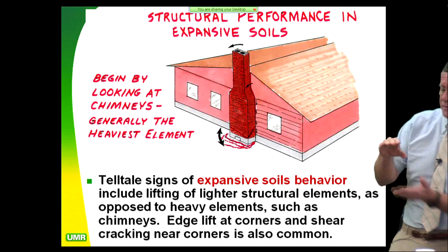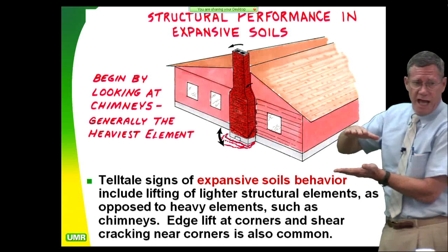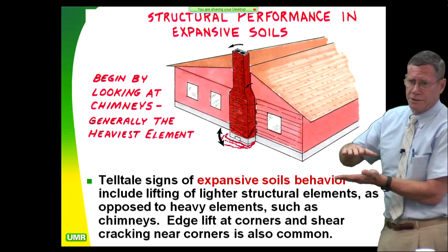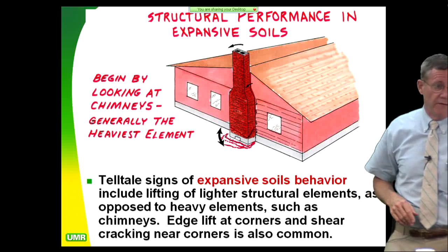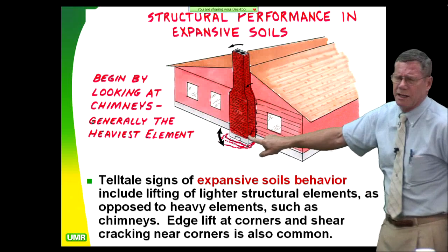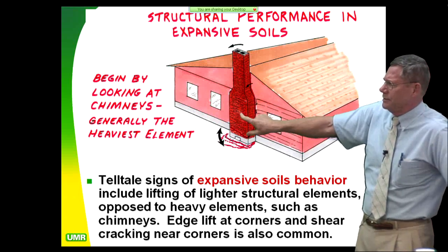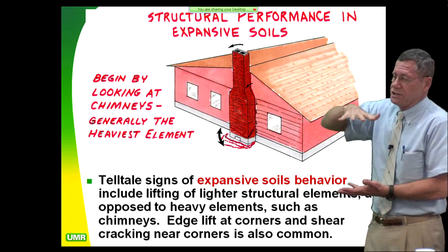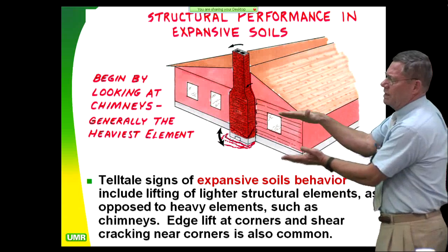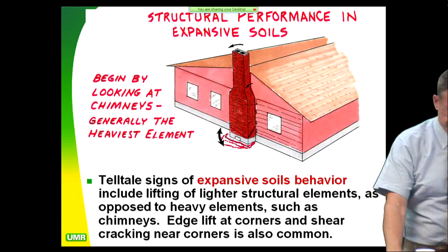And if they're double plating, like with two 2x6s, you're going to have a half inch of settlement long term due to cross grain shrinkage. And that's a lot if you're going up against brick. Brick doesn't settle a whole lot, by the way. The brick does not shrink. So if you have steel elements or brick elements or masonry elements, they're not going to shrink, but the timber framing is going to shrink. So you will get tearing between the two.